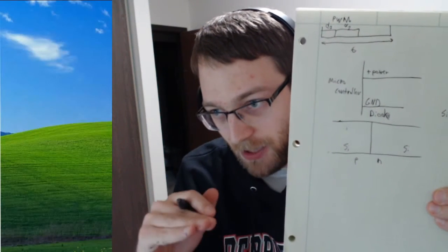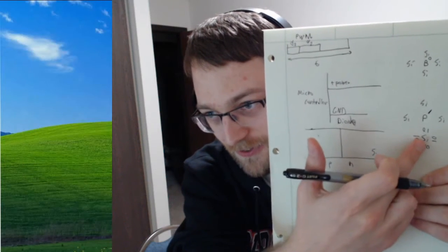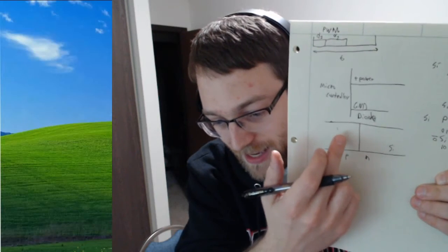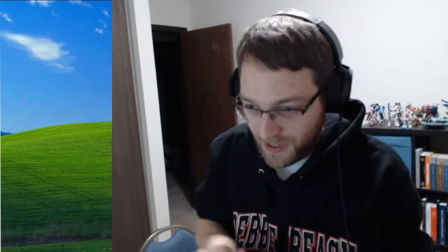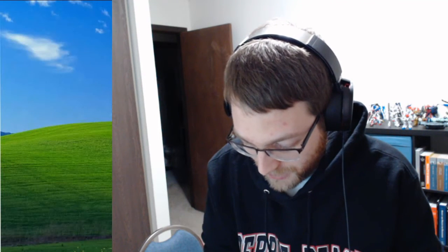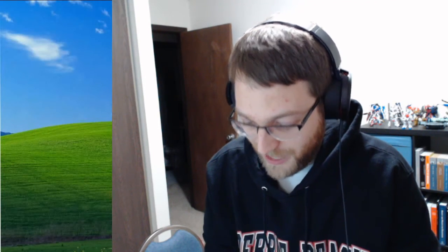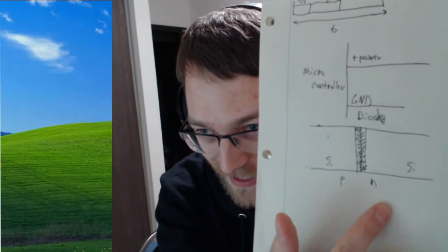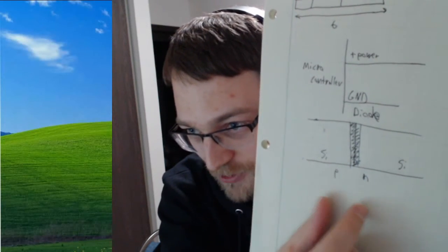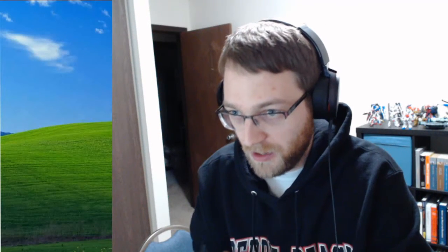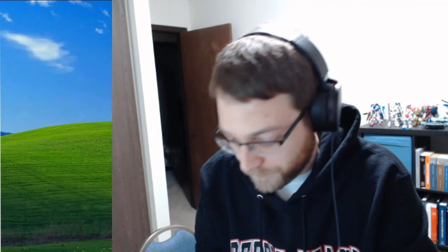It'll sort of raise it up a little bit, and then on the N side, you'll introduce a lot of phosphorus, so you'll introduce a lot of extra electrons, and it'll bring the intrinsic voltage of that side down. And right at the bridge of those two, you'll get this sort of no man's land, like a waterfall, where electrons are falling off the N side and going over to the P side, and this creates an intrinsic voltage there that must be overcome for any current to be able to flow through the device in one direction.